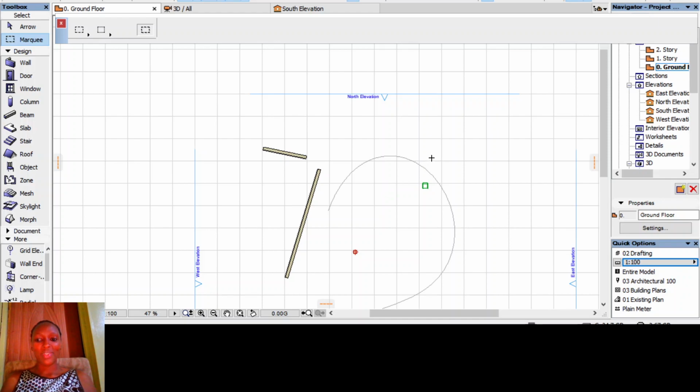All right, so that one was easy. That is nice that we have been able to do. So you can also use the scale pop-up from the Quick Options. After setting a scale, what you see will be a preview of the project if printed or plotted at that scale. So everything that we are able to see is this object, if plotted at a scale of 1:100.